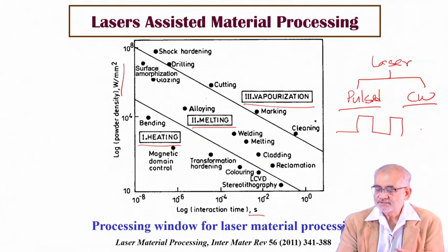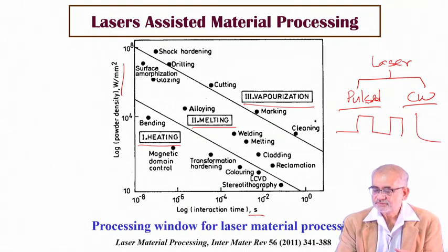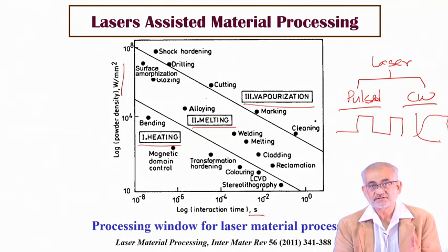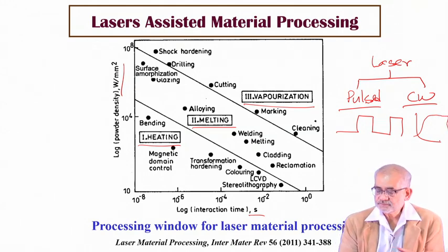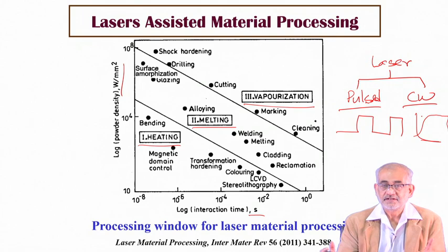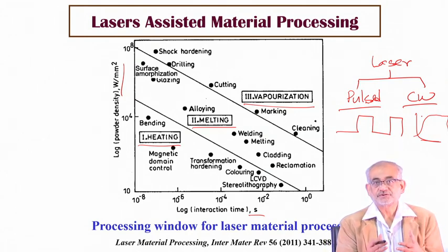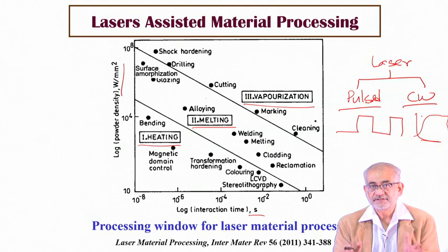On the other hand, the continuous wave essentially means that once the beam is on, it will remain on for a certain period of time. During this period, the temperature will constantly increase and heat will propagate, and the material as a whole will see an extremely high rise of temperature, and one needs to control it so that ultimately the solid is not destroyed.